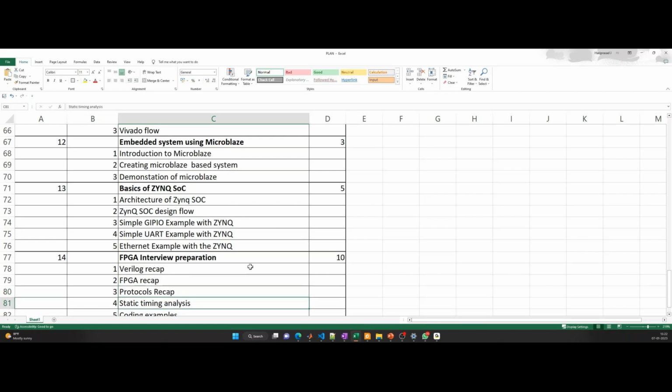See, actually in ASIC, you have a lot of flexibility. Wherever you want, you can place and route. If there is any timing violation, you can adjust the placement and routing. But in FPGA, it's very complex because all the logic gates are already fixed. You cannot move them here and there. With the given real estate, you have to build that.